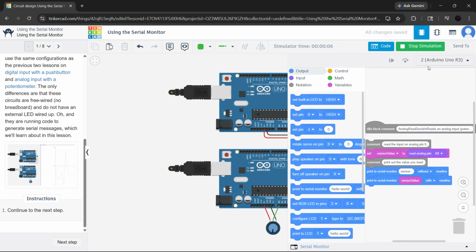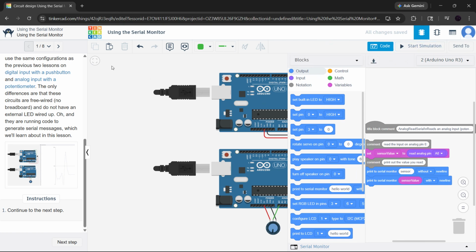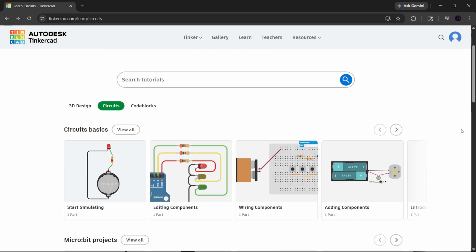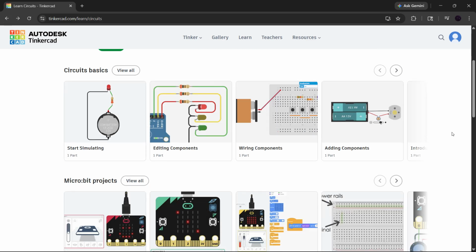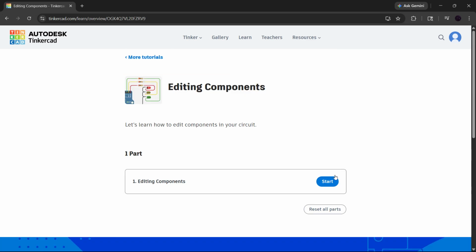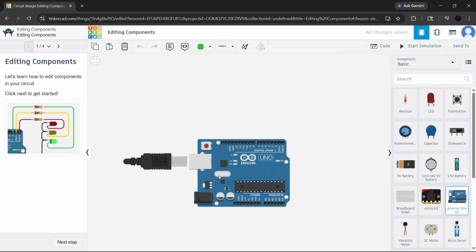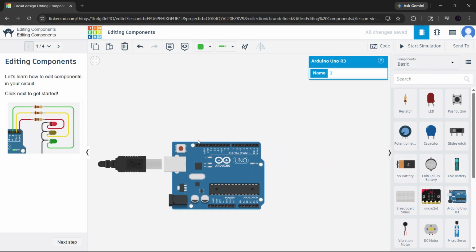The third part of the workflow is to experiment on purpose. Once you finish a lesson, break it. Change a resistor value, swap a component, alter a wire connection, make a controlled mistake and see what happens. This is one of the fastest ways to learn because it helps you understand cause and effect. For example, if you change a resistor and the LED becomes dimmer, now you understand resistance more clearly. If a button stops responding after you move a wire, you'll understand how that connection affects the circuit. This kind of hands-on experimentation is what turns basic lesson following into real learning.